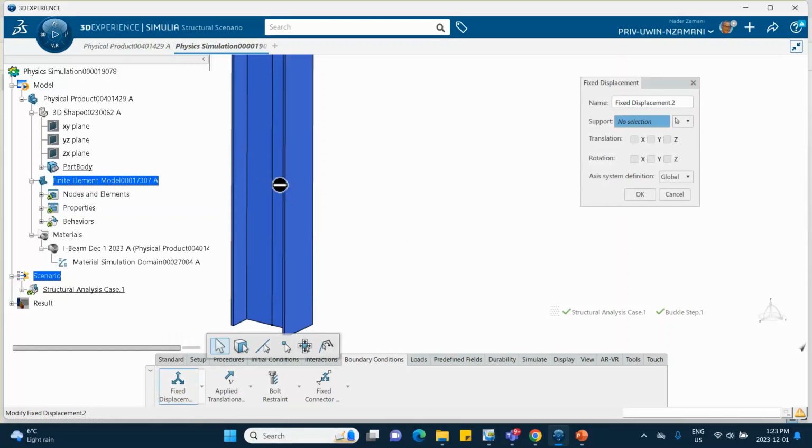You select this line and say this line does not move. That is where the beam elements are, okay? This is just a bonus dressing so that you can see it, but the beams are actually on this line, okay? Elements on that line. So it does not move in the direction X, and rotation about Y and Z are fixed.